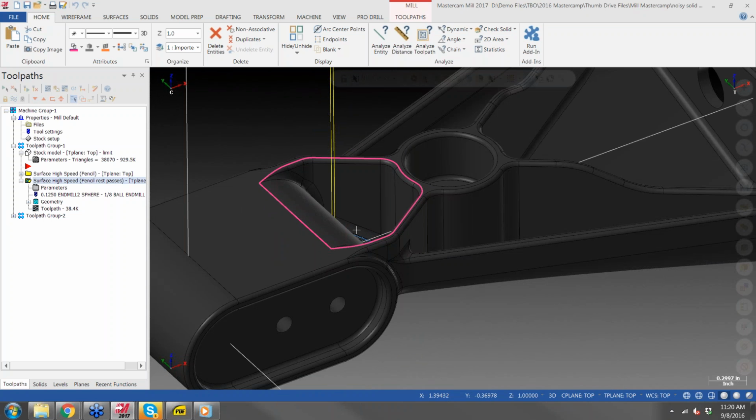I actually stopped out at a customer in Elk Grove the other day, and they were getting a really long cycle time on their UMC 750, and I was kind of showing them this trick, and they went from 3 to 4 hours on this aerospace part to just about an hour, because they were able to cut down on all the air cutting that they were doing, even using stock models prior, but they were basically forcing it to only finish the floor of this part because necessarily the walls didn't need to be as precise.